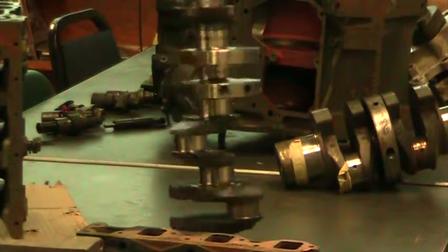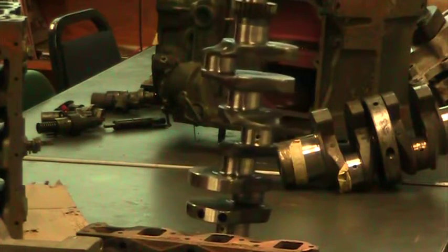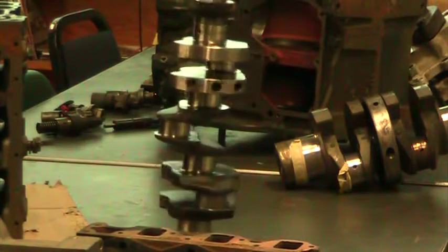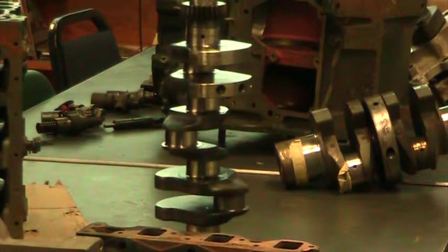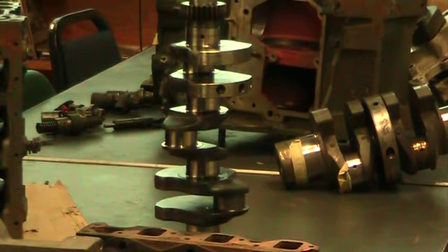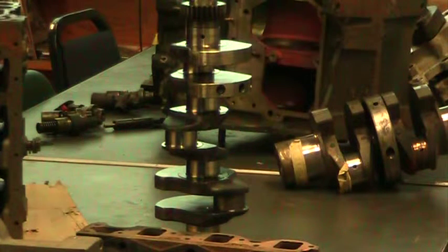So we have multiple ways. This one down here has 4 drill holes in it. This one doesn't have any. That one only has 3. Essentially they add a little bit of extra metal to the counterweights, so they know the heavier end is going to be on the counterweight side. They don't have to drill anything out of either side. It's easier to remove metal than to add it back on. You can't weld on it to add weight, but we can remove it by drilling pretty easily. So they add a little extra and then balance it out.